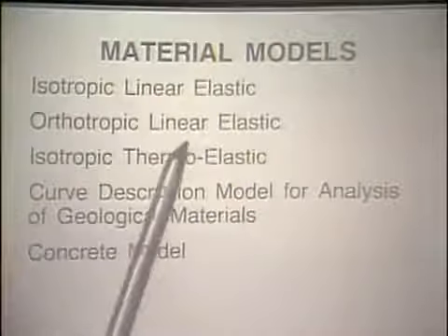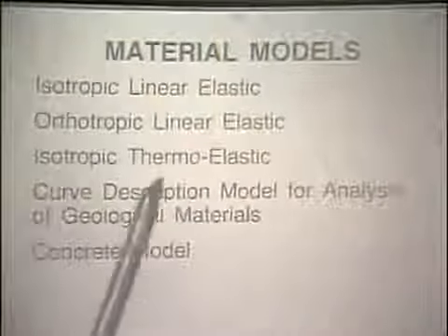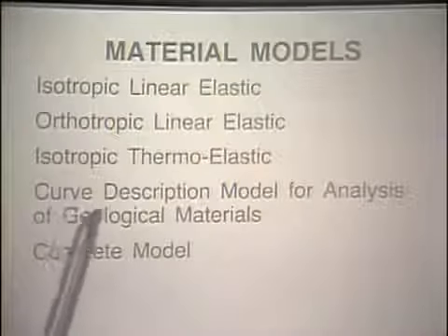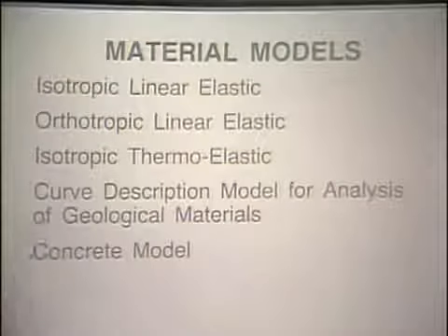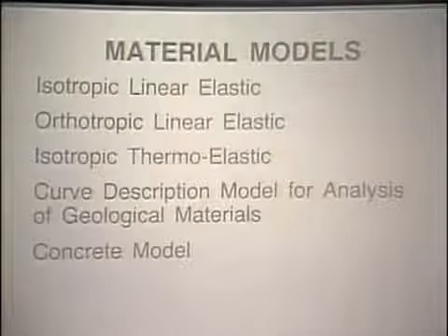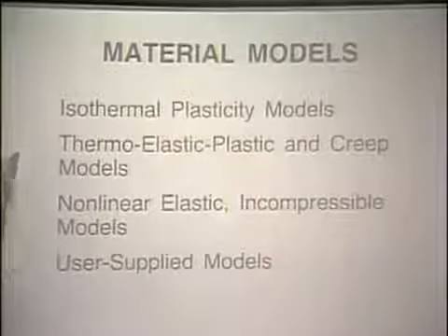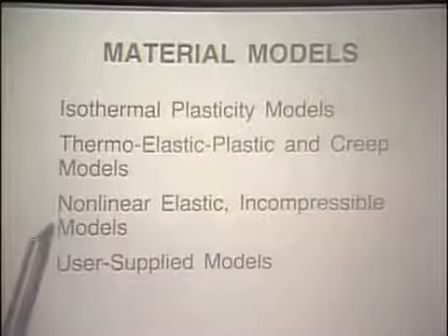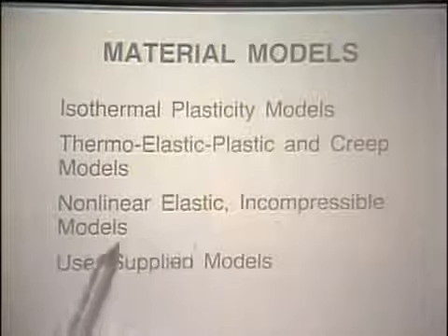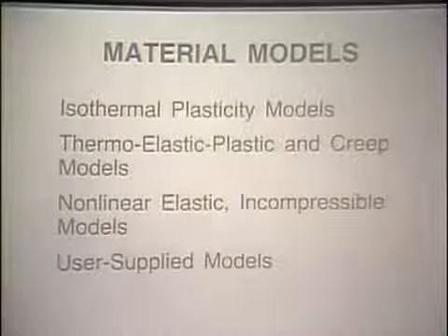Material models that are available: an isotropic linear elastic model, orthotropic linear elastic model, isotropic thermoelastic model, a curve description model for analysis of geological materials, a concrete model, isothermal plasticity models, thermoelastic plastic and creep models, nonlinear elastic incompressible models, and user supplied models.